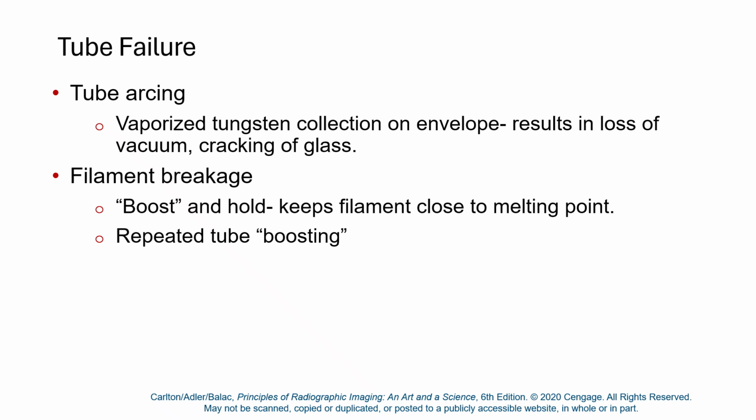Once the vacuum is lost, your X-ray tube is gassy and it's basically non-functional as far as a modern X-ray machine goes. Filament breakage. Boost and hold, excessive prepping, can cause damage to the rotor bearings, but more likely it's going to cause your filament to overheat.